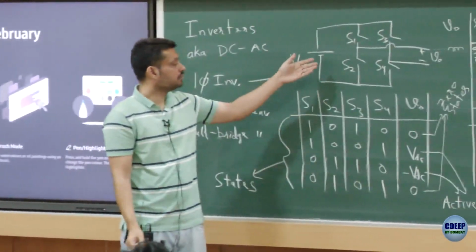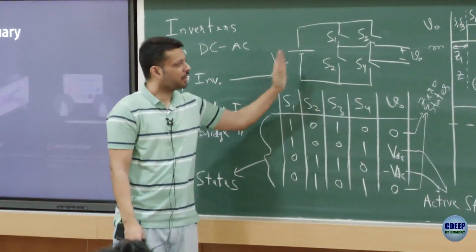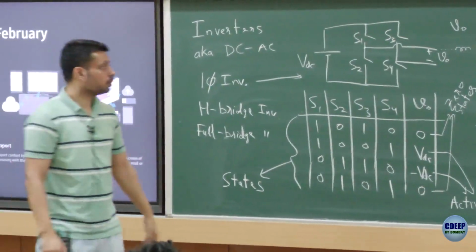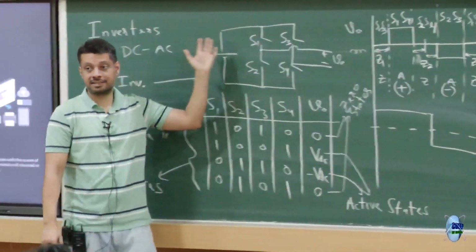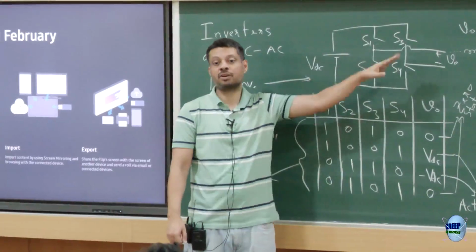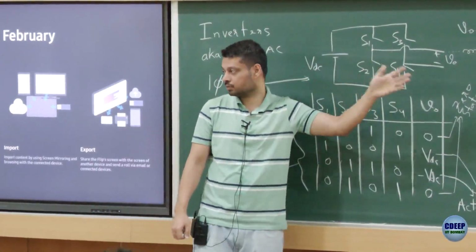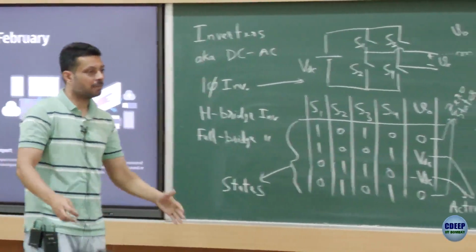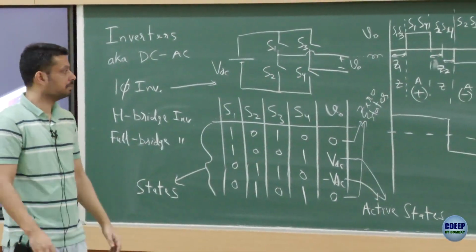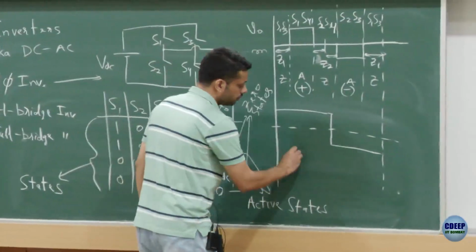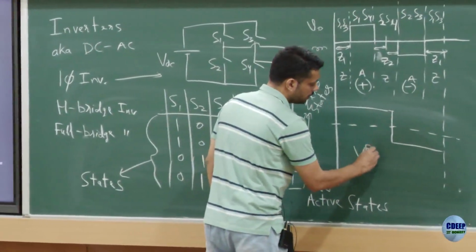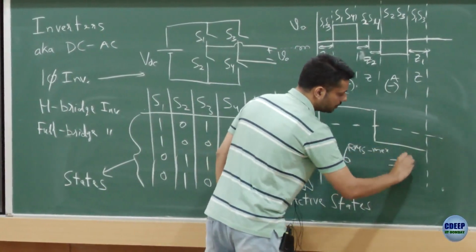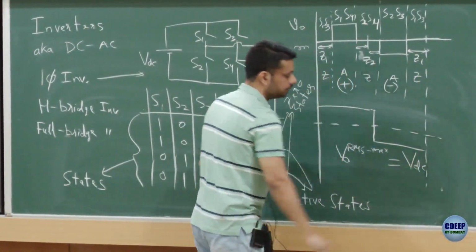Right? So, you can keep reducing the voltage. It's not, let's not call it a buck converter or something, but you get the idea, right, that the output RMS voltage is limited by the supply DC voltage, and you can always produce smaller than that. You cannot produce more than that in this kind of circuit. So, yeah, it's not a buck converter, but you get the same sort of feel here, right? So, V output RMS max is equal to VDC.